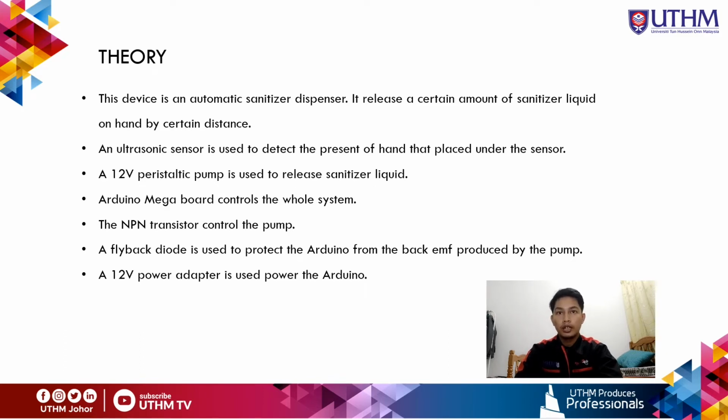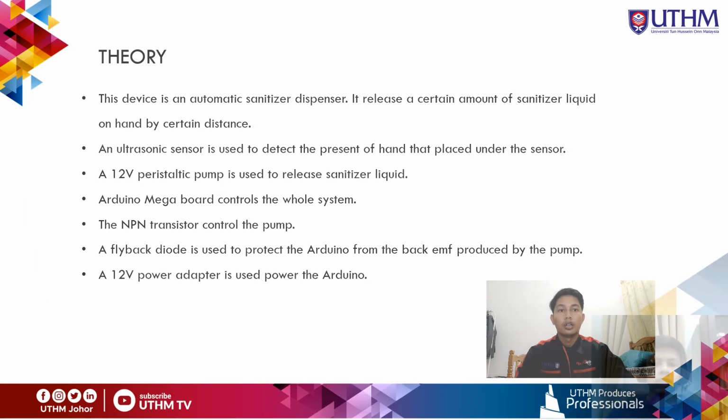An Arduino Mega board controls the whole system. The NPN transistor controls the pump. A flyback diode is used to protect the Arduino from the back EMF produced by the pump. The last one is a 12 volt power adapter, used to power up the whole system.